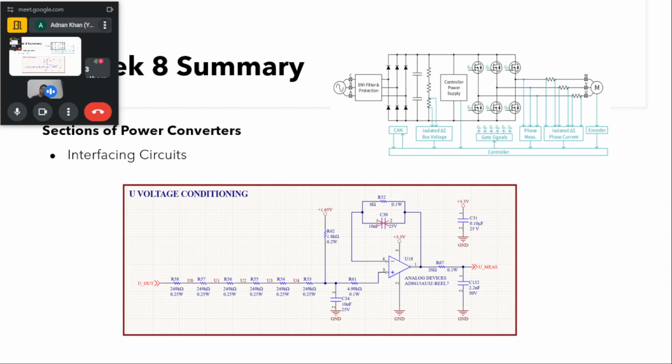Also, if we want to change our voltage, let us say after this voltage sensing part, the voltage that we got was in the range of 5 volts or 10 volts or 12 volts and so on and so forth. But we know the voltages that we can give to the microcontroller range from 0 to 3 volts.